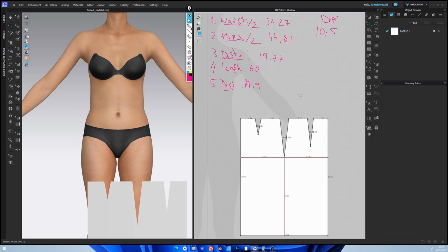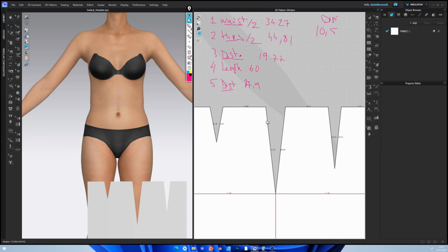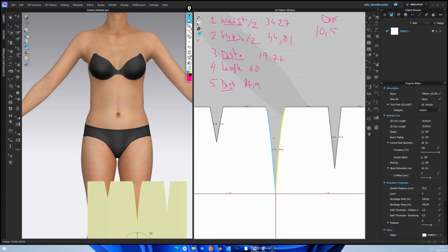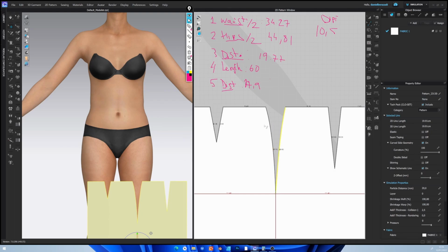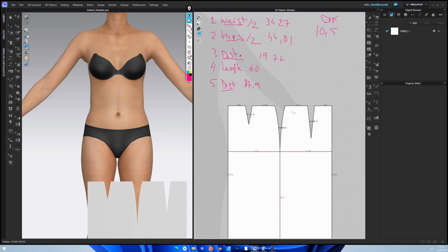Right, so we're going to curve the line on the hips. I'm going to choose edit curvature, the simplest one, so that it flows a little more natural. With the darts, it's not needed because they will be in a flatter area, but this, since it's going to be on the hips, should be rounded a little bit. It doesn't have to be super rounded, but yeah.